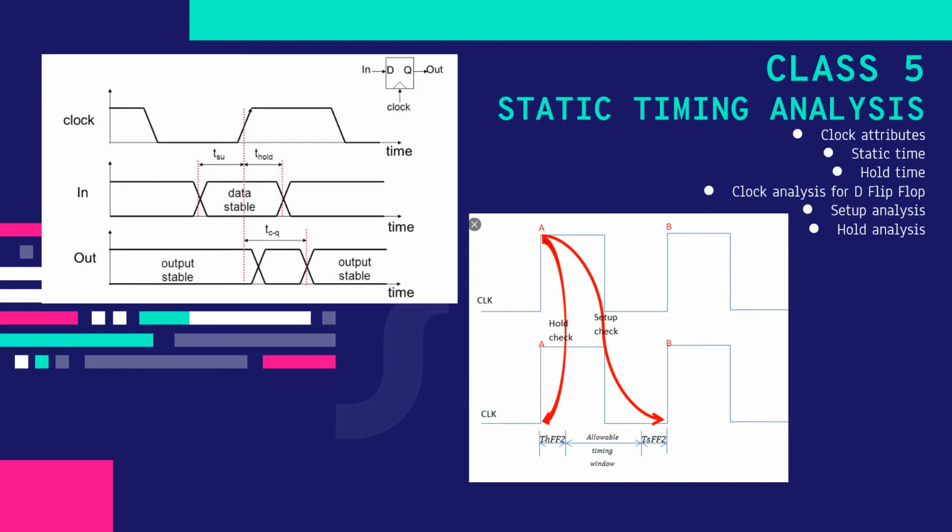We then looked into clock analysis for a D flip-flop. We learned about clock to out, that is TCO, also known as the clock to Q, which is defined as the time delay from the active edge of the flip-flop's clock input to the resulting change in the Q output. We learned how every device path in a design must be analyzed with respect to timing specifications or requirements. Designers must enter timing requirements and exceptions. We learned about the different paths present in an FPGA, for example, register to register, or you have your data path as well as your clock path.